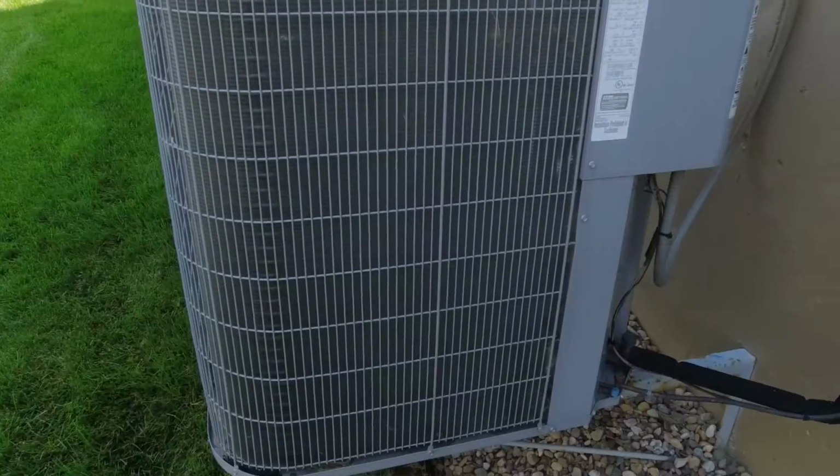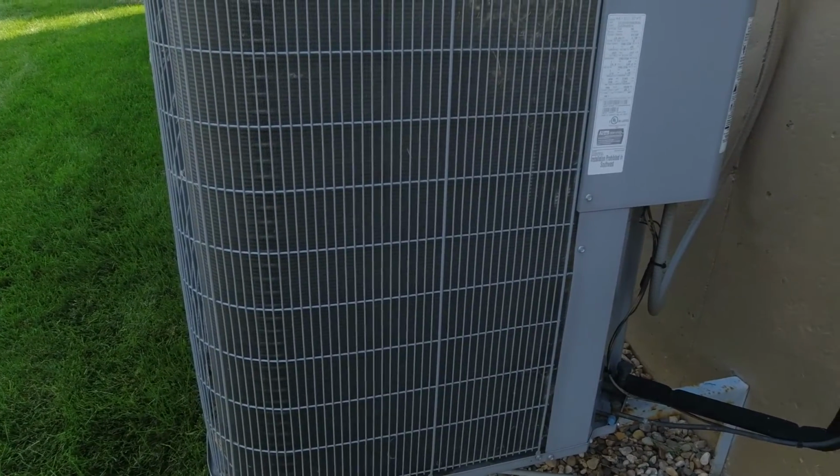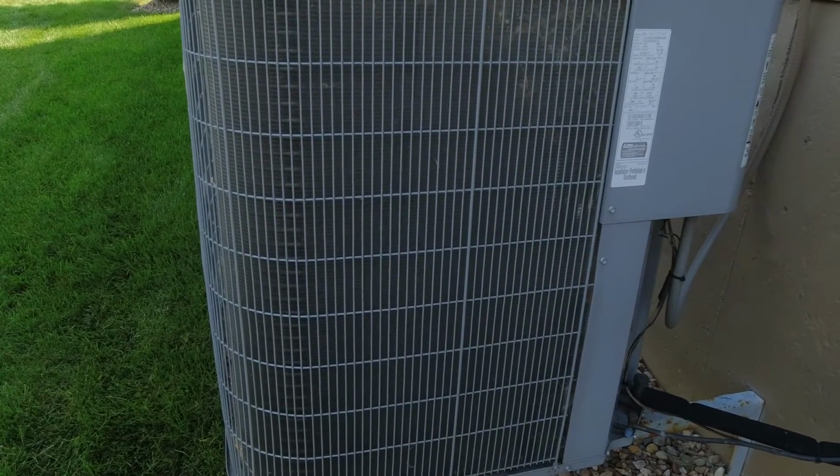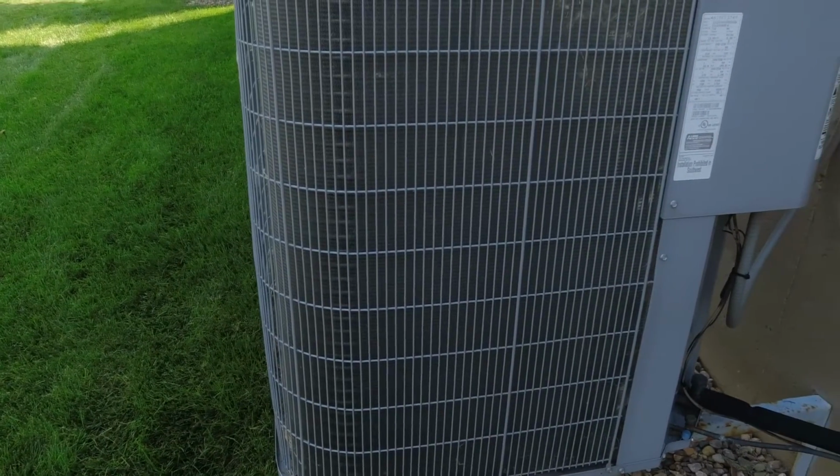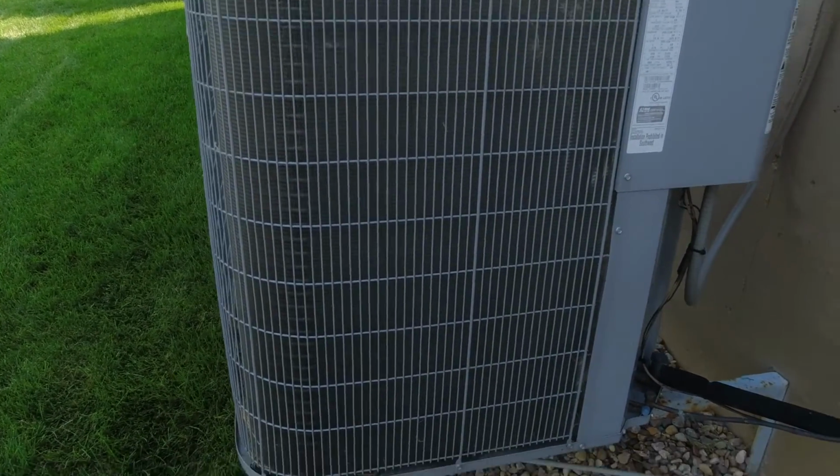Okay. So now if you can hear, the compressor isn't running, just the fan. So you heard that really short start. Yep. There, just did it again, a little whomp. That means the compressor is trying to start, but it's not able to. So what's happening here is the outside fan is running and the compressor attempts to start for just a second and then immediately shuts off again. And you can hear that short start of the compressor turning on and then back off again.